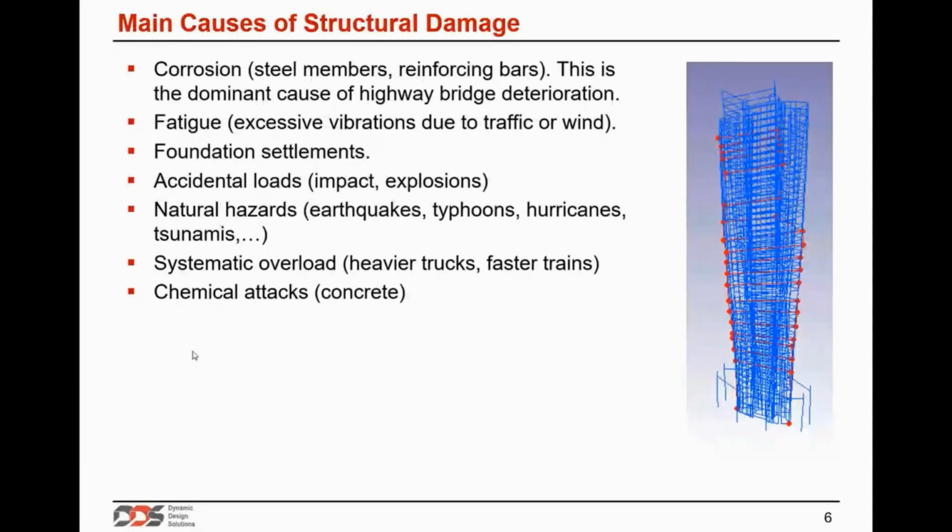So the goal of using simulation models and updating reference simulation models can be to identify structural damage, which can be caused by corrosion, fatigue, foundation settlements, impacts, earthquakes, typhoons, overload, or chemicals. So this is just the different types of damage that can be causing the change of the vibrational structure.